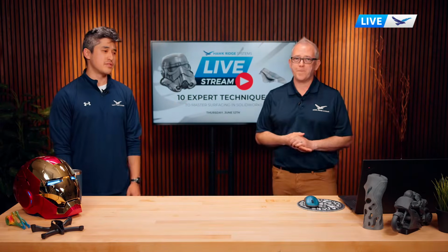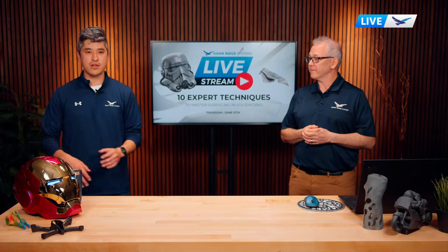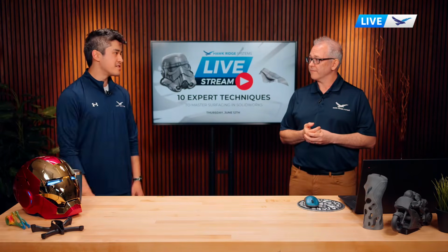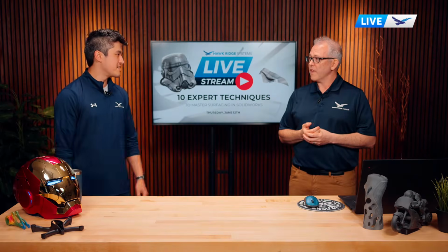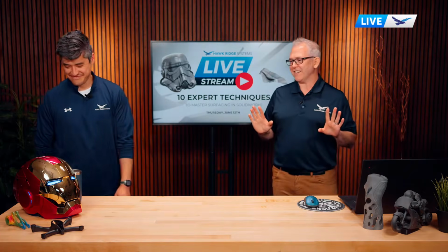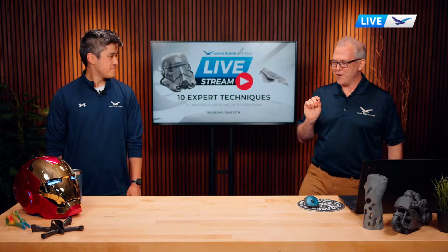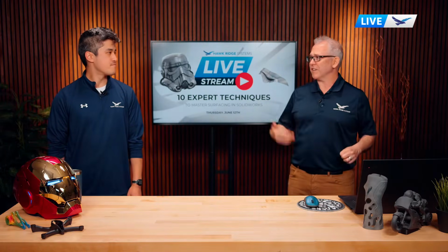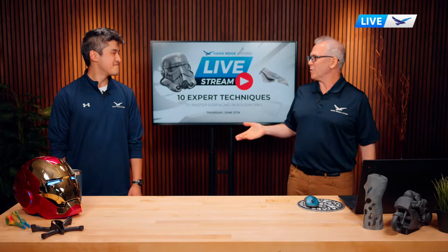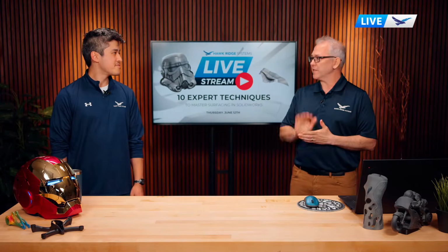Yep. And so not only for your own ability to continue modeling, but sometimes you're going to need areas that you know are dead flat for some kind of manufacturing process or tool pads or whatever, and just knowing 100%. It's also just a super simple tool, right? In my older age, I like to make sure that the tools I use, I know how they're going to behave 100%. So even if there was a line and a surface extrude, is that plane flat? Well, if the line was flat, yes. But what if I modify that surface later? Then maybe not, right? So using this planar surface, I know it is going to be.